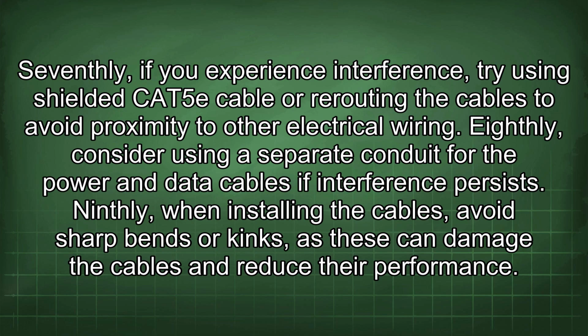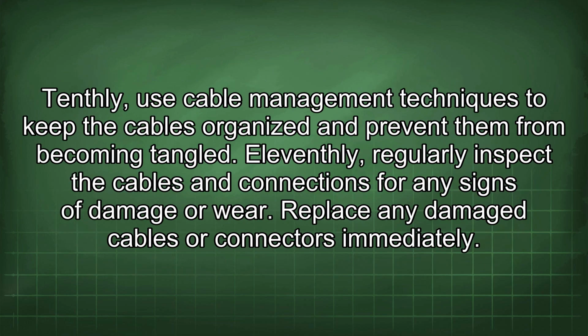Ninthly, when installing the cables, avoid sharp bends or kinks, as these can damage the cables and reduce their performance. Tenthly, use cable management techniques to keep the cables organized and prevent them from becoming tangled. 11thly, regularly inspect the cables and connections for any signs of damage or wear. Replace any damaged cables or connectors immediately.